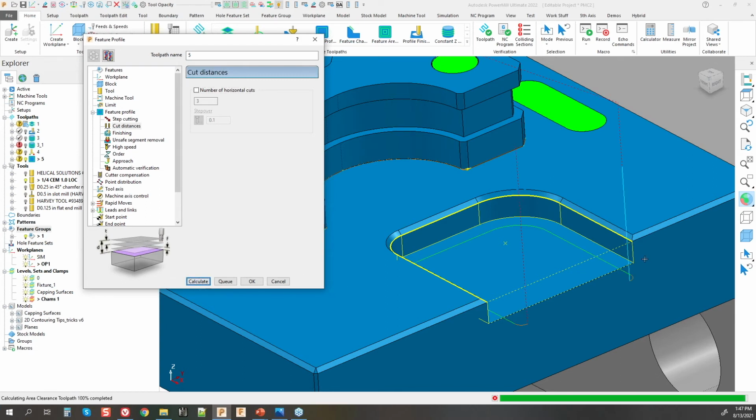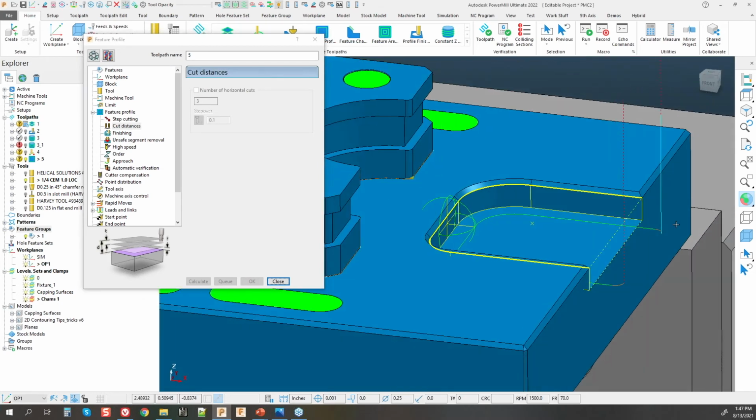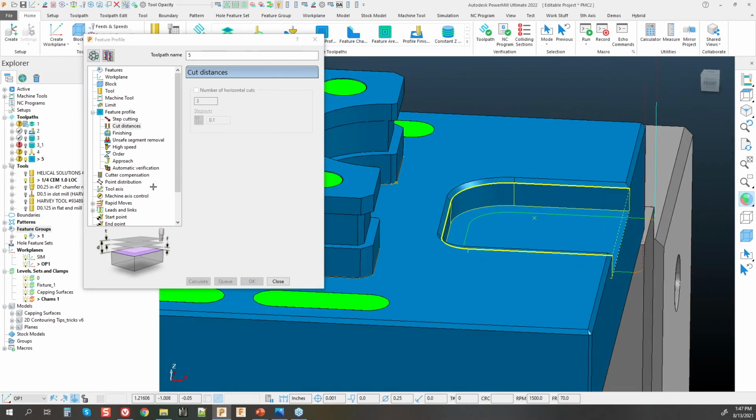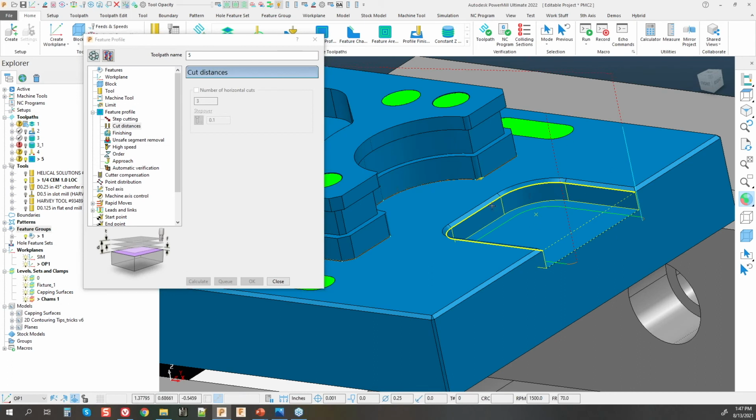you'll find that that's going to calculate itself to the feature depth, but also give me an outside profile area that allows for a little bit of lead in around the selected features. Features are pretty good at doing this and managing it. It's just about the selection that you use for it. Now, like I said, this is a usage case scenario, where if you want to control this feature well, tolerance-wise, or to print rather, features have actually been really helpful to me for those use cases.